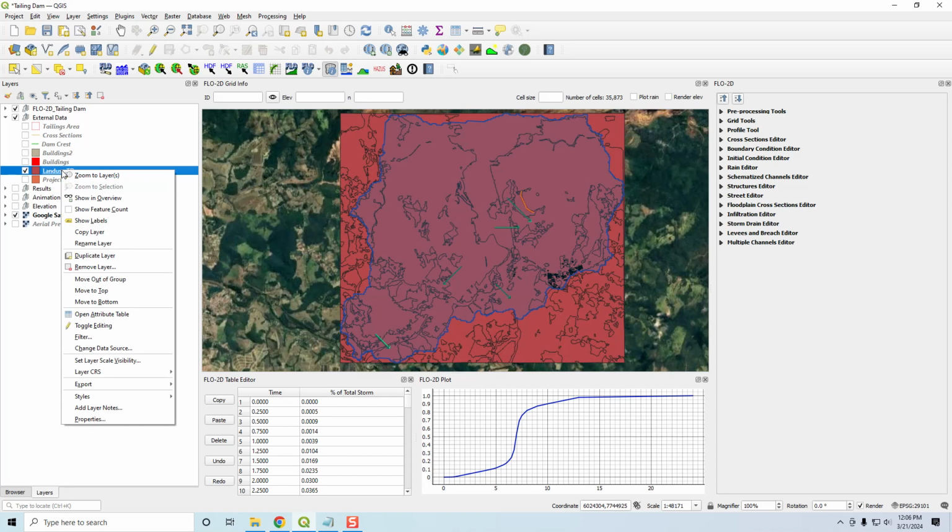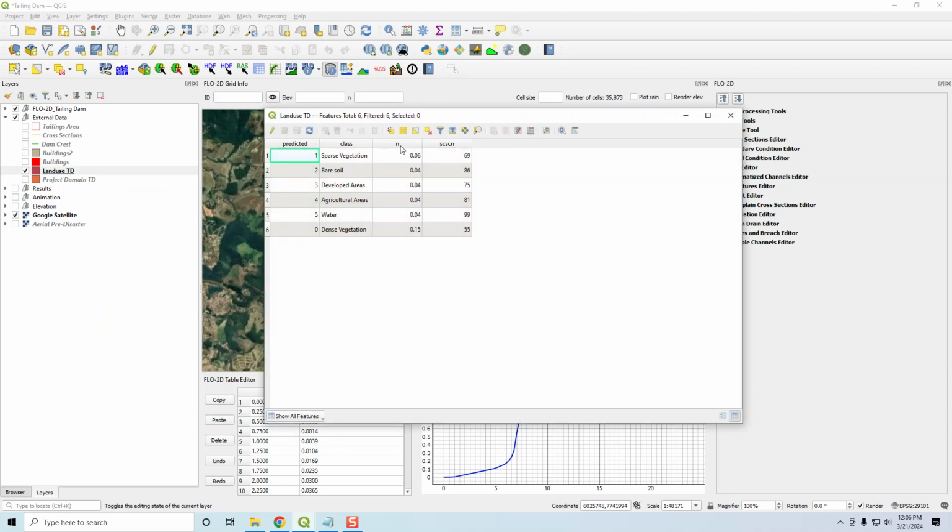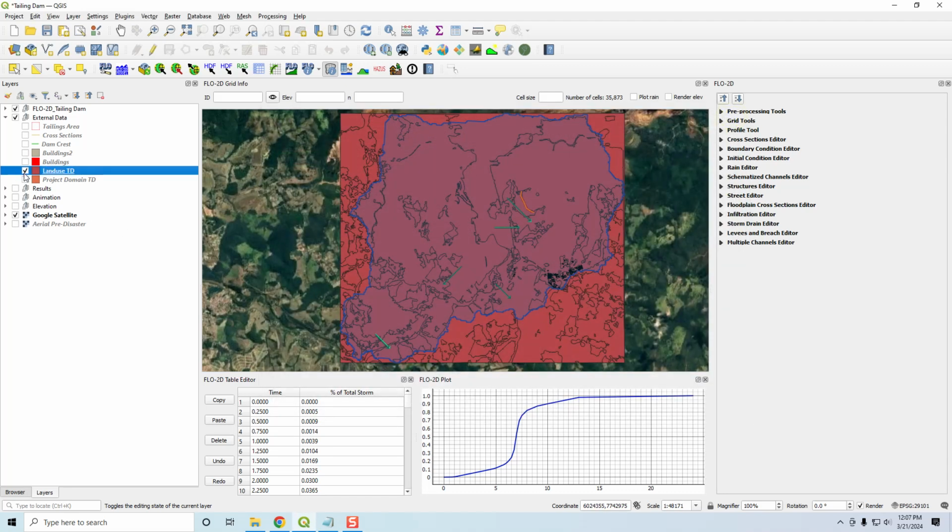And what we've done with it is, let me open the attribute table, we have modified it with an N value column where we estimate an N value for these different types of land use, and a curve number column where we have used some of the soil properties, upper horizon soil properties, and land use imperviousness to create a curve number for this data. And again, all of this is in the class, so I'm not going to go over how we developed these parameters because it's part of the class, and it just takes too long.